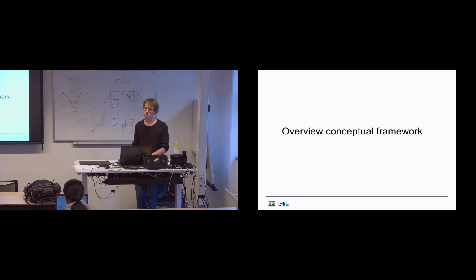I just want to ask, is this flexible mesh a totally independent software from Delft3D? Largely, in terms of hydrodynamic kernel, yes. But there are modules that we share, like the morphology module to calculate sediment transport. That is shared between Delft3D 4 and flexible mesh. But how the bottom update happens is specific for every model, because that has to do with the geometry of the grid. So there are things that are shared.